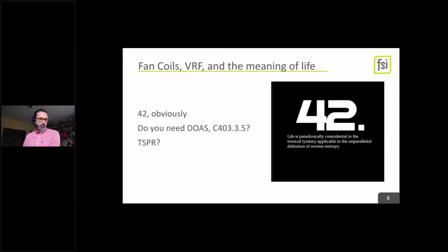So for fan coils, for those hydronic things, you might be able to keep that hydronic in place. We'll talk about what you have to do on the hydronic side when we get down there. You might also replace them with VRF again. It's a really flexible system that is making retrofit a hair easier in most cases. The exception being extraordinarily tall buildings. VRF has a height limitation. You can only go up 8 or 9 stories and down 10 or 11 stories.